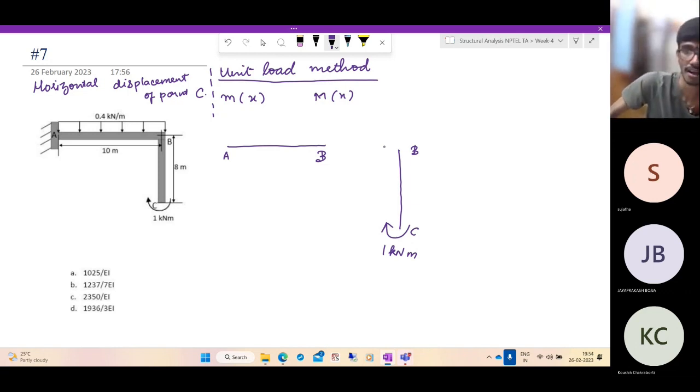Yeah, right. So at B, you can have... So this is a free end. So there is no other unknown force that is acting here. At B, you can have a force like this. They call it Bx. Force like this, By.